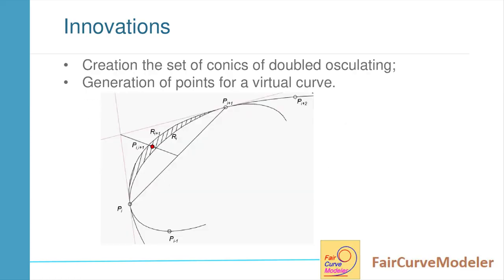The mathematics of C3D Fairing modeler is based on parametrization. With its help, we generalized the concept of spline as a set of curves that have equal geometric parameters at arbitrary points of the base polyline. In conventional splines, the parameters of the curve are equal only at the junction of spline segments.